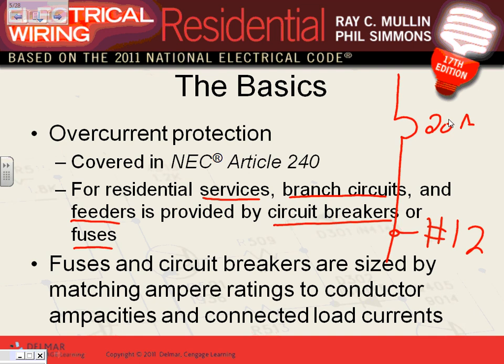12 goes with it, right? Okay. So what we're saying here is that current, under normal condition, can go up to non-continuous, up to 20 amp in this conductor, and this conductor will continue to operate fully functioning, right? Are you with me? Up to 20 amp circuit. Overload, we're fine. Non-continuous, up to 20 amp.